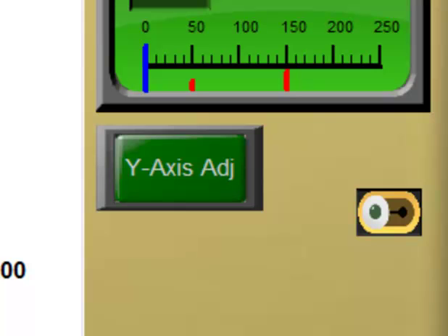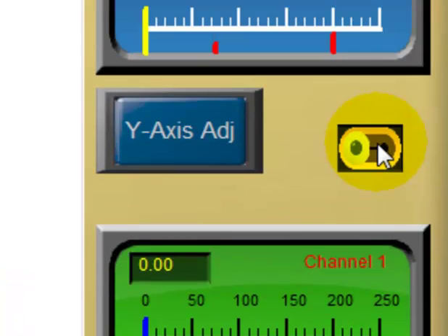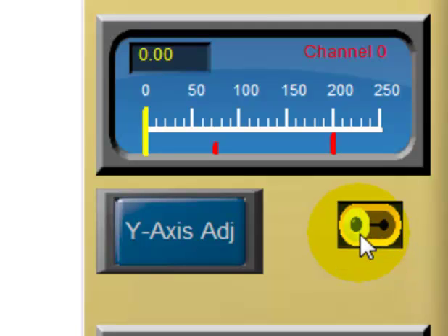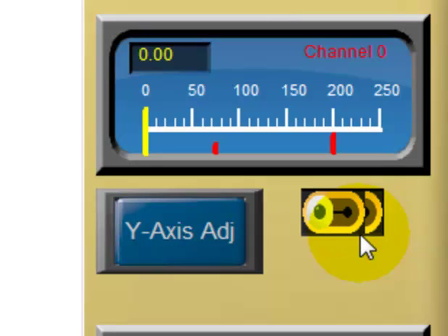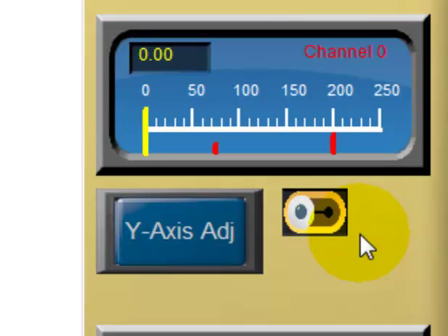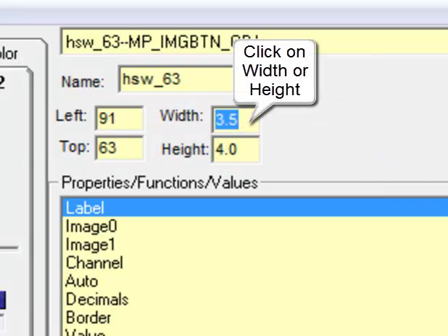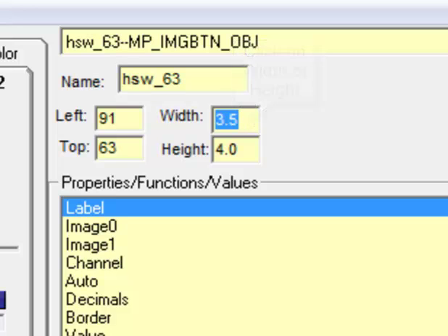Let's start with the one under the top meter. Once again, pushing the shift key, right clicking on our mouse key, and now what we can do here is move it up to where it ought to be. We'll use the arrow keys to do it that grossly. And what we also want to do is change its size, make it a bit longer and perhaps deeper. So come up here to the width control, and now we can use either our arrow keys or enter a width into the text box.